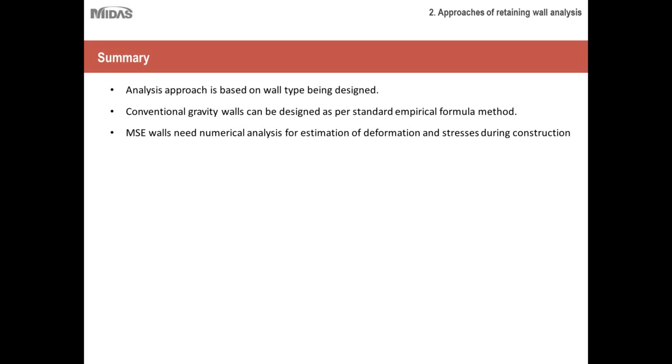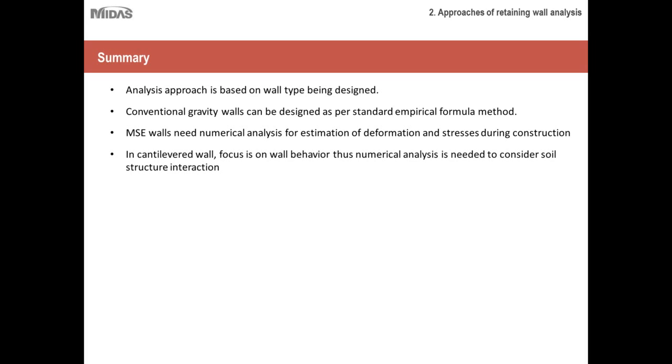For MSE walls, we need numerical analysis for the estimation of deformation and stresses during construction. In cantilevered walls, the focus is on wall behavior, thus numerical analysis is needed to consider soil structure interaction.